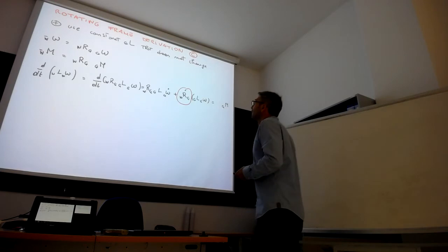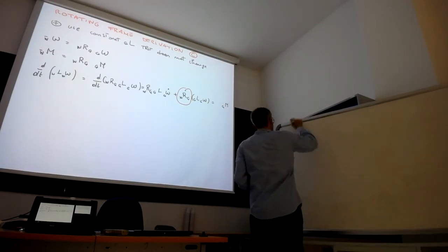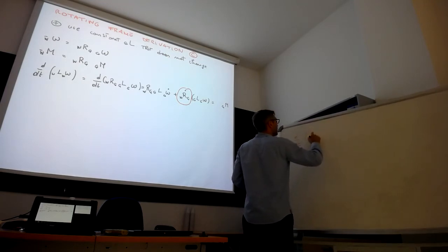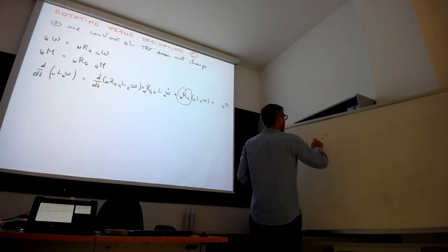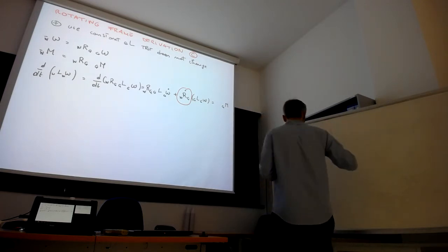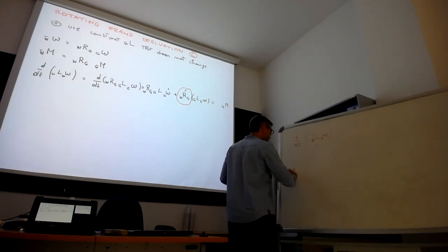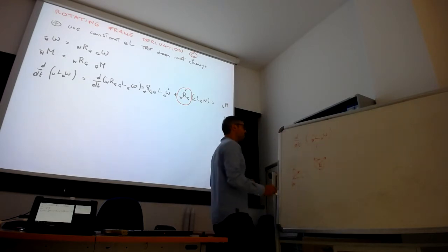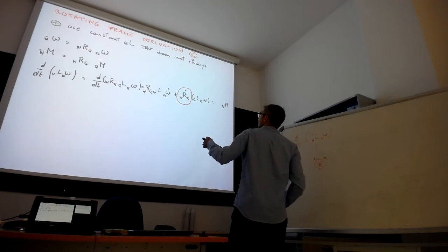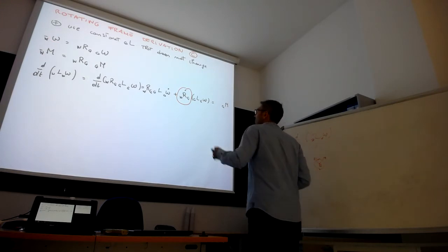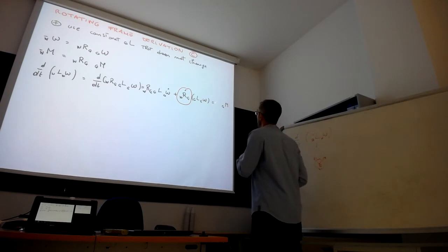So this time we start from the previous formulation, where we have L_W omega_W, and we replace it by computing the angular velocity expressed in the rotating frame. So now we are thinking about the inertial frame here and a frame rotating with the body, attached to the central mass. So this frame is rotating. And with the rotation matrix, we can map the angular velocity in the G frame into the world frame. And the same for the moments.